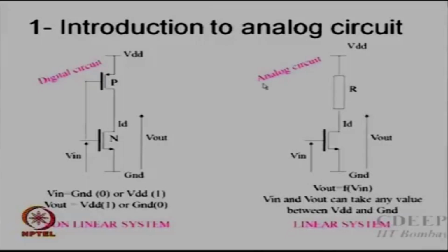Whereas if you look at analog, the basic circuit is an amplifier. Okay. Actually this is also an amplifier, there is no difference. I will show you what is the difference. This is an amplifier which has a resistor, which can be a transistor as well, and you have an N-channel driver. Please remember the word driver is used by us, which receives input and puts the output.